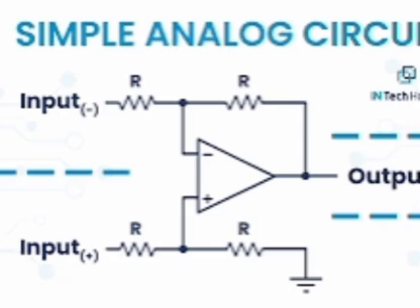Applications of current mirror. The current mirror is used to bias BJT in IC amplifiers. Current mirror can be used as active load in IC amplifier. Advantages of current mirror biasing: it requires smaller chip area than self-bias circuit. A current mirror is equivalent to a constant current source, hence the DC collector current of the bias transistor remains highly stable.